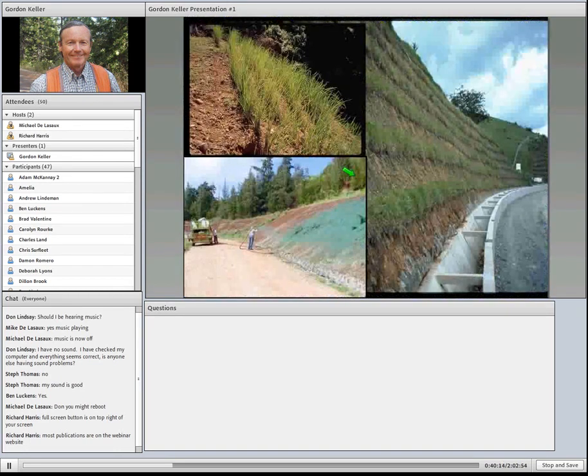Here's some examples. Even conventional erosion control, particularly with good grasses and maybe mixed with some deeper rooted type of brush, may be more than enough to prevent a failure or to fix a small site. These other treatments up on top, this is a vetiver grass, which has a very deep root. It's not native, obviously, to the U.S., but people like the World Bank use it a great deal in various countries. But the point is, it's got deep roots, and it's pretty. It's not native, but it's also not invasive. And then this is some grasses that were planted into a cut bank, which was raveling.